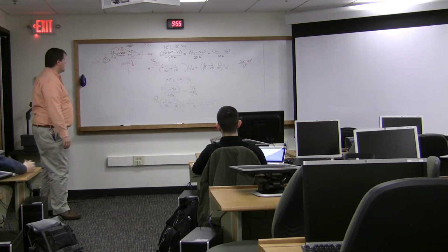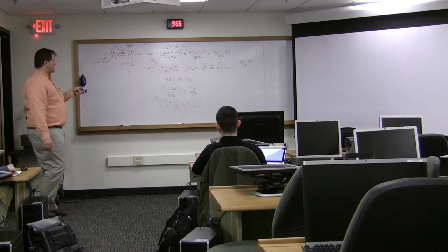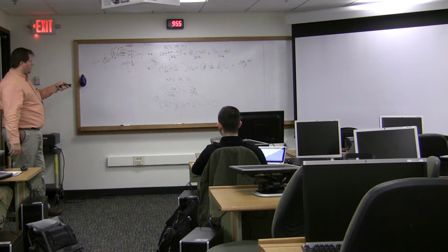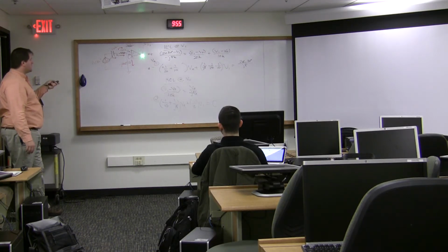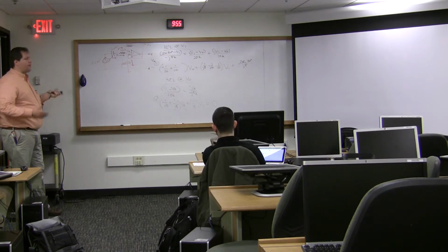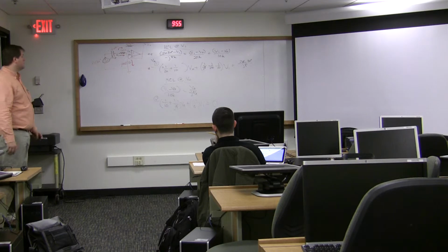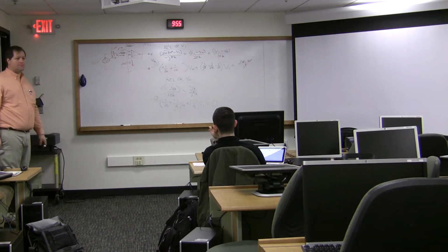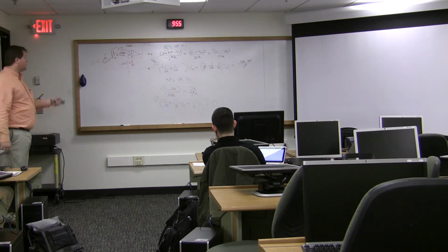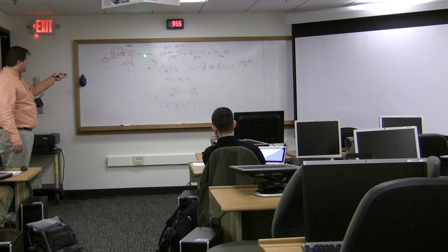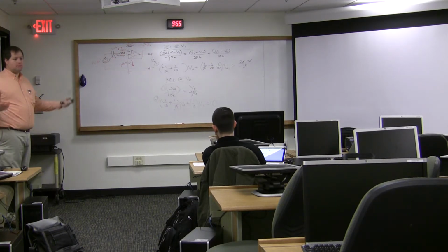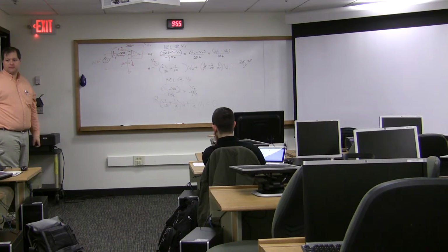Okay? Once I solve this, it's going to spit me out a little matrix with V0 and V1. V0 is the output voltage we're looking for. But then I'm also looking for I0. So how do I find I0? Once I know V0 and V1, it's just V1 minus V0 over 20K. So once you've found the 2 voltages, the current is pretty simple.